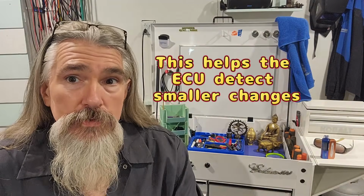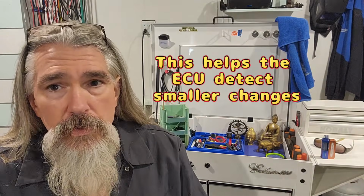So we'll just say our number was 50, where it was. Instead of having to go from 0 to 50, it'll remember 50 from last time. So that way, if the value is 55, it only goes up 5, from 50 to 55. That's where it's giving you where it looked last and where it's looking now. If it were the standard way, it would have been from 0 to 50 and then from 0 to 55. So you see that's 105 units the computer would have had to measure as opposed to just 5. So that's how it works. And it could work great for you finding the misfires.